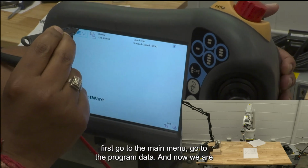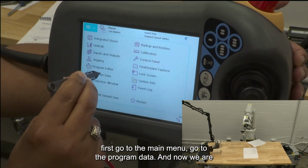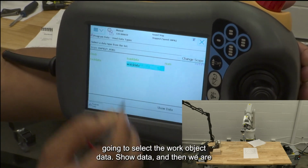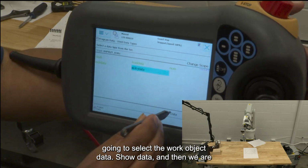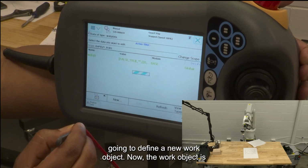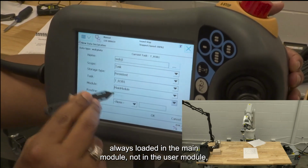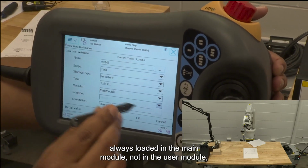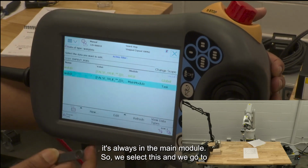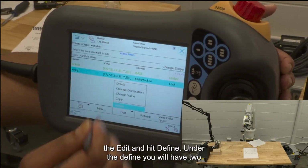So, here what we are going to do is, just like how we did for the tool coordinate system, we need to first go to the main menu, go to the program data, and now we are going to select the work object data, show data, and then we are going to define a new work object. Now, the work object is always loaded in the main module, not in the user module, it is always in the main module. So, we select this and we go to the edit and hit define.